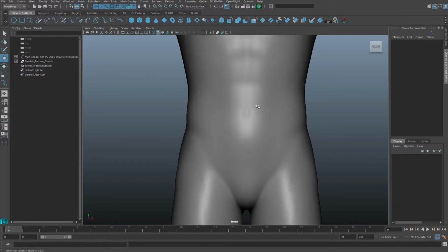Making zombies trouser. Now we'll make the zombies custom pattern with Maya's curve tool. First, in order to make the trousers belt, select the EP curve tool on Maya's shelf panel. Then draw the first curve from the center waist in counterclockwise.